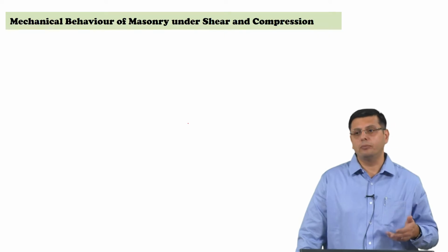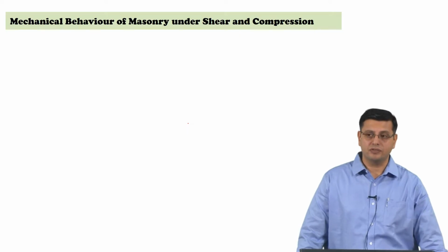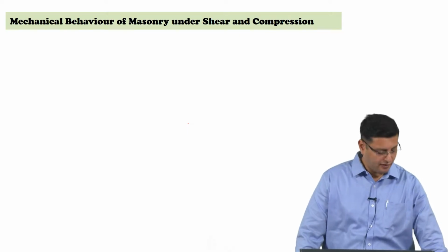Good morning. We will continue with the lecture on the shear strength under the consideration of gravity forces in the masonry. We were looking at establishing a set of expressions that for different levels of axial compression give us a failure surface in terms of shear mechanisms. So, we had looked at the first of the cases based on the basic formulation of Mann and Mueller.